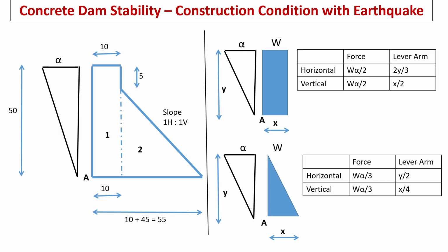Now we will see load combination involving earthquake. Seismic coefficients are denoted by alpha. It is assumed that the seismic coefficient varies with height in a triangular pattern, with 0 at bottom and maximum at top. Depending on the respective country standards, these coefficients are multiplied by factors such as 1.5 or 2 times to incorporate safety. Here in our problem we are directly taking seismic coefficients without any factor.